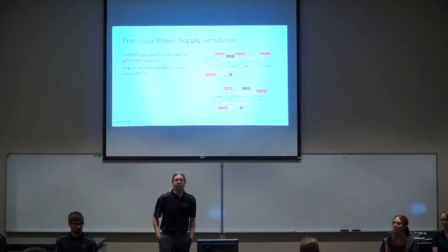The processor supply circuit was modeled here. In the top diagram, the 5 volt DC source is straight from the voltage regulator to the processor, and it feeds the BeagleBone Black, a temperature sensor, and an ultrasonic sensor. In the bottom diagram, the 3.3 volt source is one of the pinouts from the BeagleBone Black, and BeagleBone Black powers the FLIR Lepton and the transceiver. As seen from these simulations, there's a relatively low current draw throughout the circuit as well.